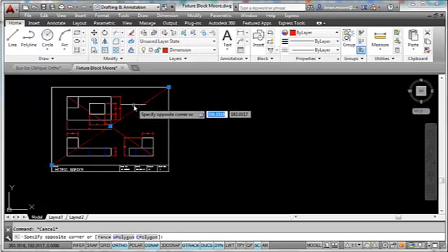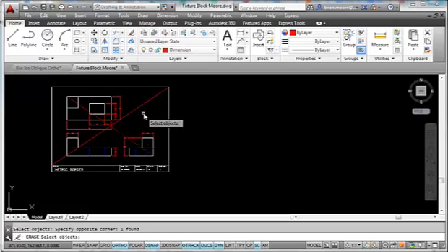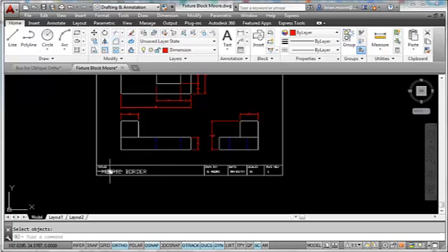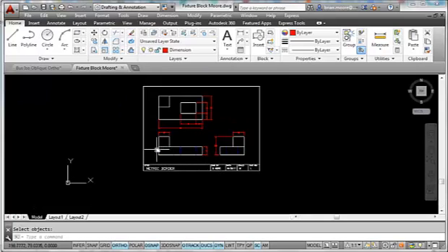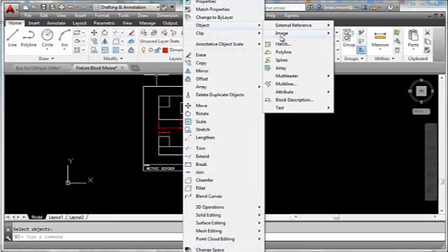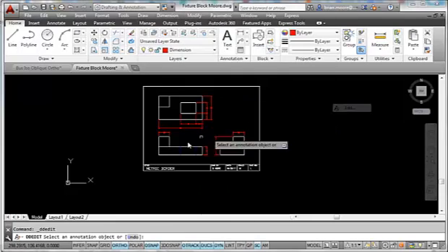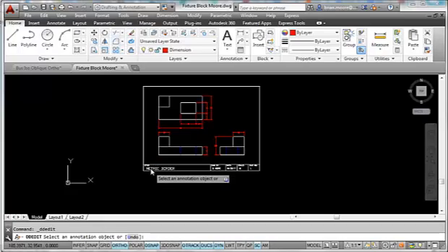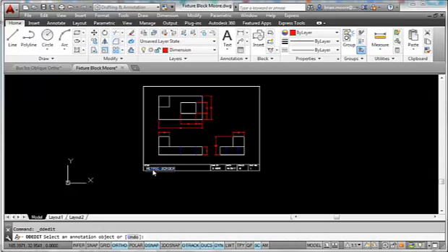We don't take the dimensions into account when we center it, so I've got it properly centered. And I would go and change my title, the date, and the scale will still be the same. This one I'll go modify object text edit. You can just double click on it. And I'll call this one Fixture. I need my caps lock button on.